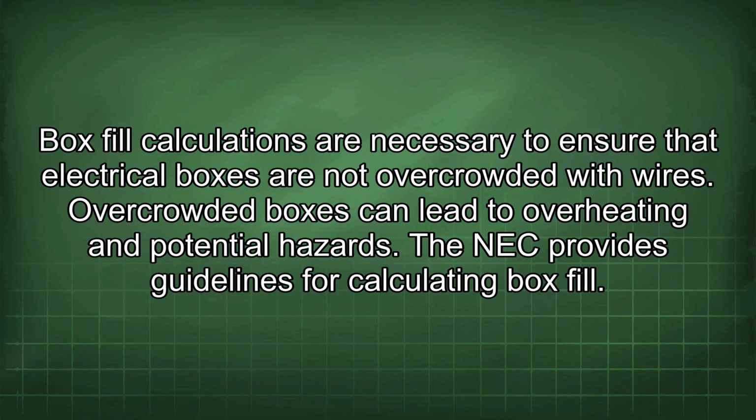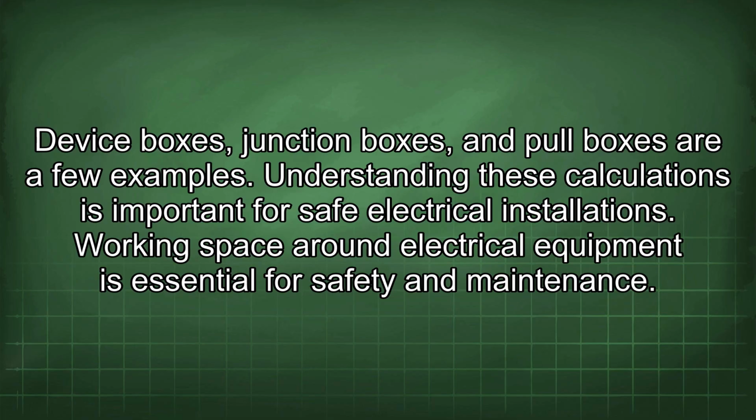Box fill calculations are necessary to ensure that electrical boxes are not overcrowded with wires. Overcrowded boxes can lead to overheating and potential hazards. The NEC provides guidelines for calculating box fill. Device boxes, junction boxes, and pull boxes are a few examples. Understanding these calculations is important for safe electrical installations.